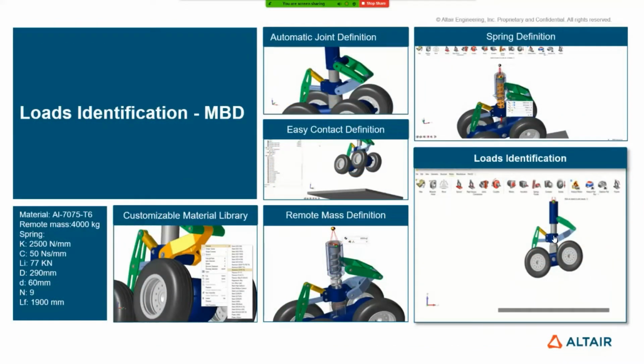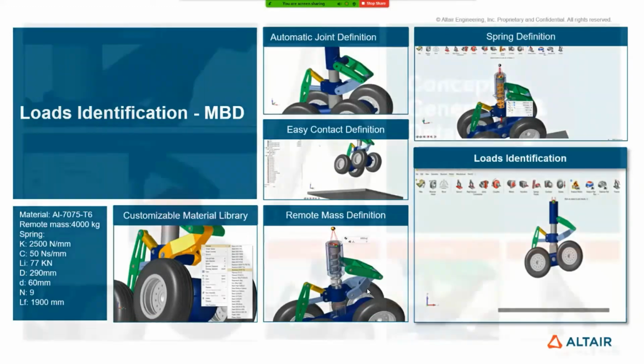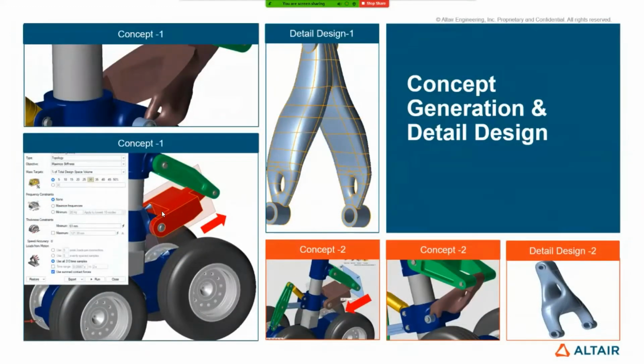If you see, that existing bracket has a different shape, that is cast. This is the one that has been converted to what is called design space. Now, what is design space? Design space is essentially the maximum available space of a component to an engineer, which they can go to the extreme, how much maximum area they can take to design a component. That is design space, and that's what has been done over here with the red block. What you are seeing is a conversion from the existing design to design space.